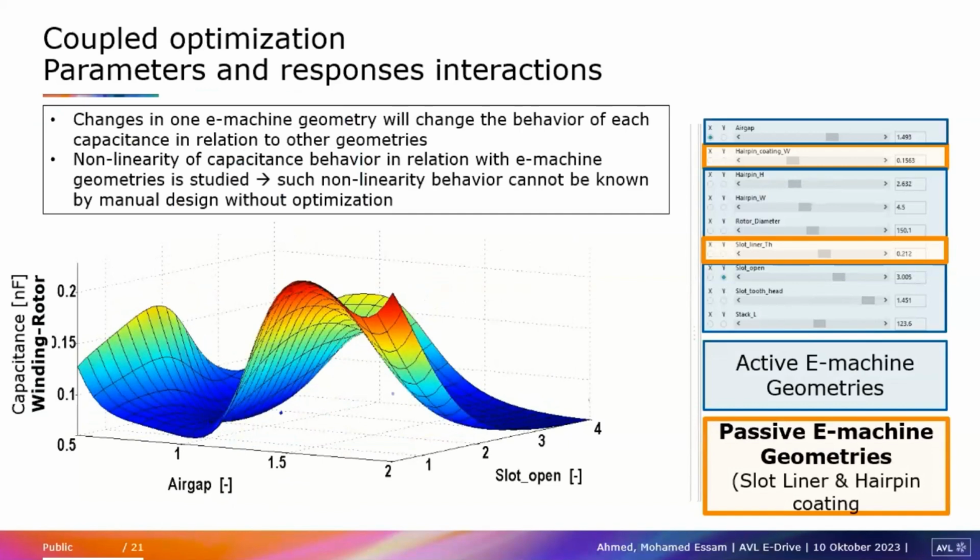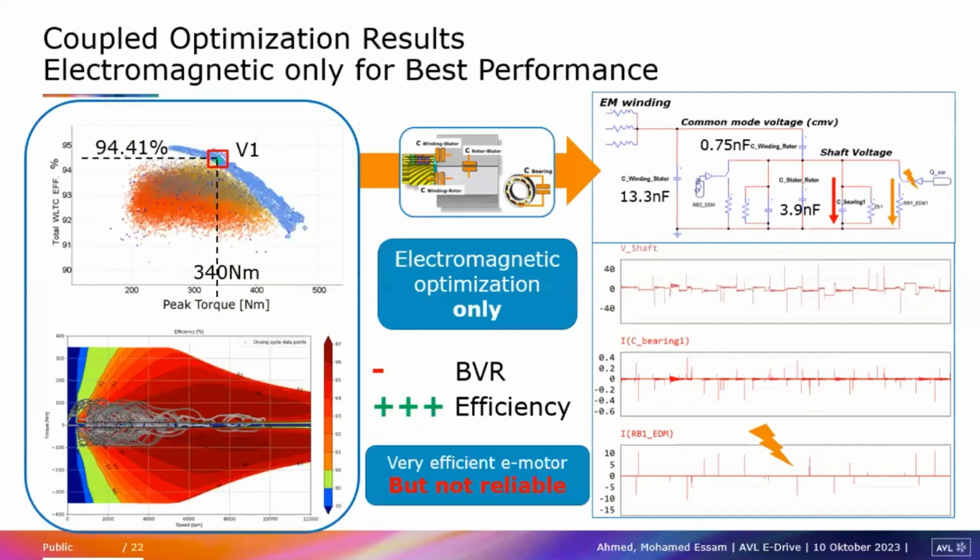Question from my side. You're dealing much with capacitive current for the bearing current. Since I see it's quite high frequency, I'm wondering, there is also serious inductance in the distribution path of the bearing current, and this is heavily affected by skin effect, since the frequency is high and we have ferromagnetic parts, especially in the rotor. So I would expect the skin depth is less than, I don't know, 100 microns or something, which will mean you have a very big serious inductance in the distribution path, which I do not see in your schematic. And I could imagine that there is a big effect, especially in the high frequency area, that the bearing current is maybe a lot lower due to this effect?